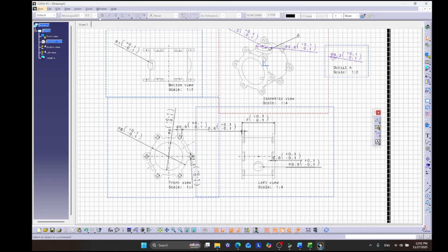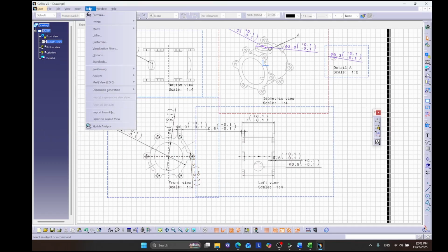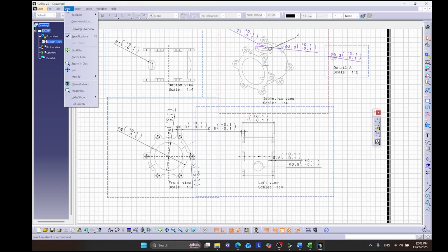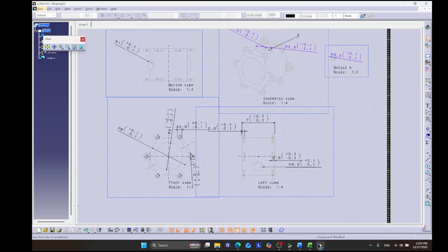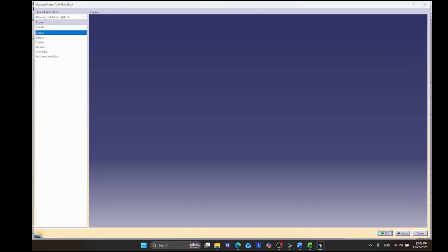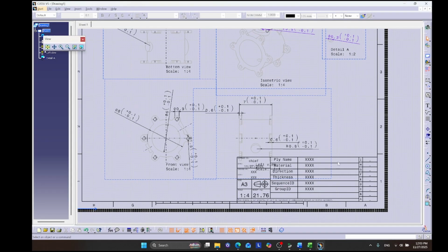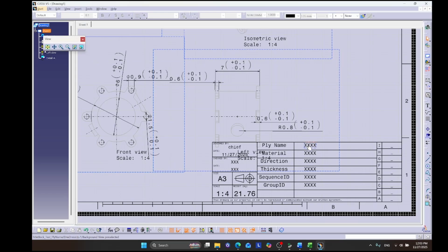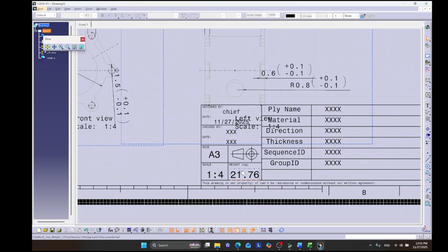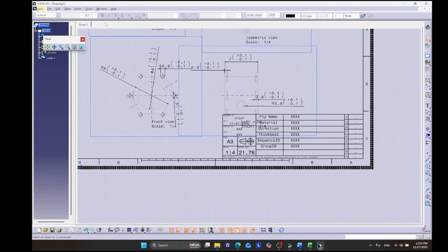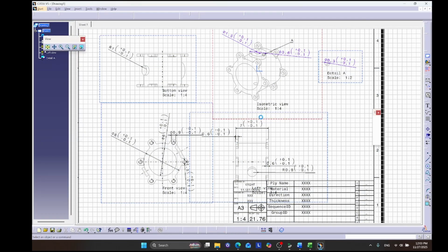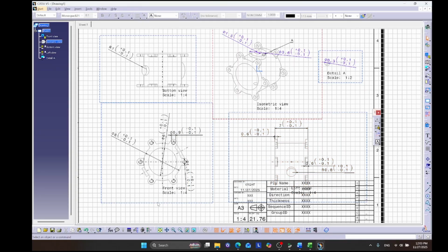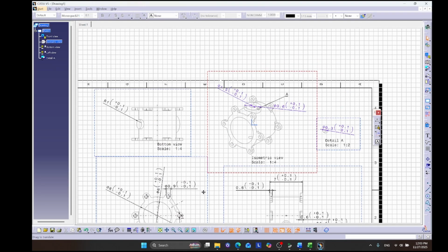Now just click off. Now go to create a title block. I will go to edit, sheet background. Go over here, this button over here. I will create a sheet background. Apply. Okay. As you can see, now you can name everything. I won't name it because it's a waste of time, but make sure you name every single thing here. And if it's stuck with the sheet background, you can move your elements. How do we go back there? We go back to edit and working views. Now you can move your elements around again, so it doesn't get stuck with the sheet background.